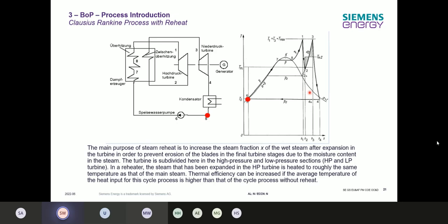So we increase the temperature again, getting to the outer side to stay out of the wet steam part as much as possible, so that probably only the last stage of the turbine is seeing a higher amount of water. And this we can prevent by protecting the turbine with a certain coating, to make sure that the blades are able to handle this.